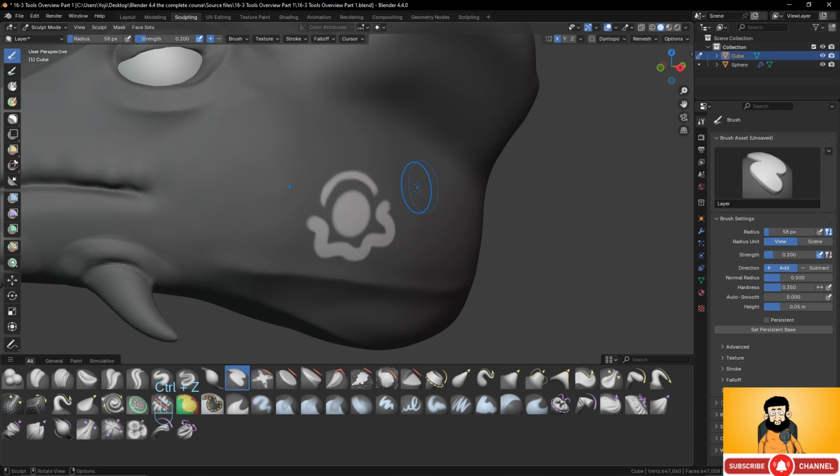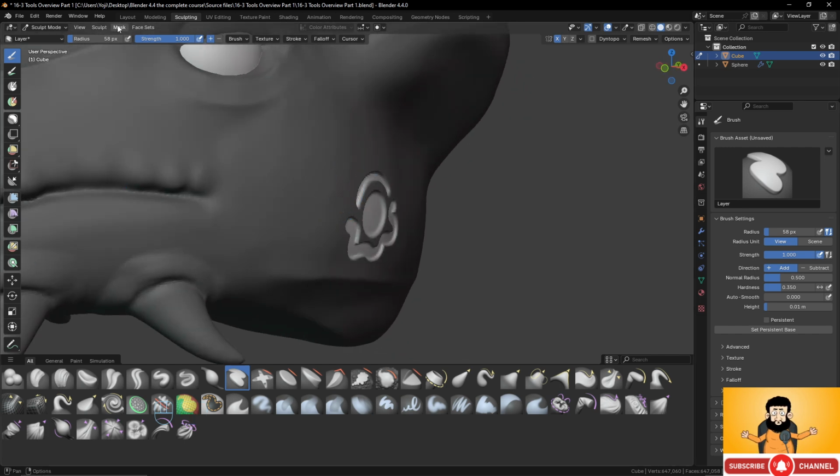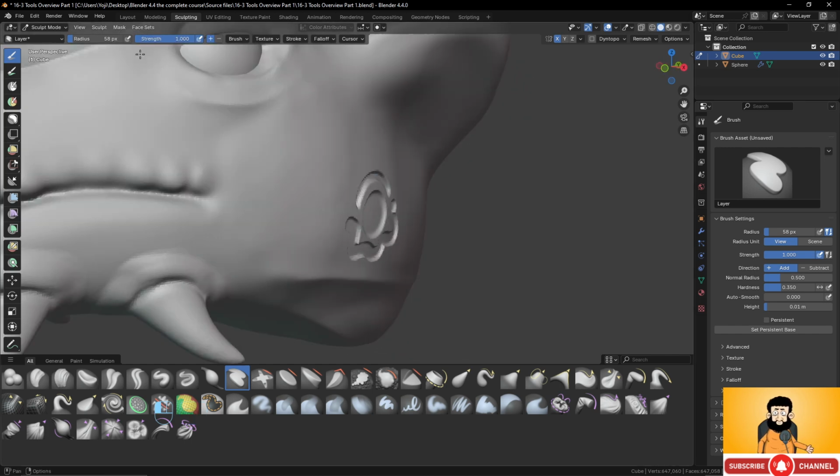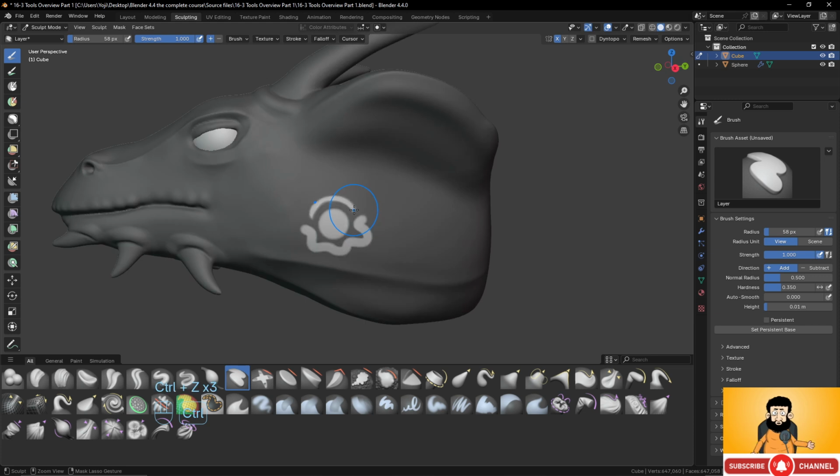Okay, and if I want to extrude inside, I use the control key like this. I can use it very easily to add some details or remove details in case I need. So I will use a depth, a height at 0.01 maybe. With the control key, I just draw like that, maybe 2 times. Okay, and I come back with the mask and clear mask, and now I will have my details. So very easily you can again add some details into your object.